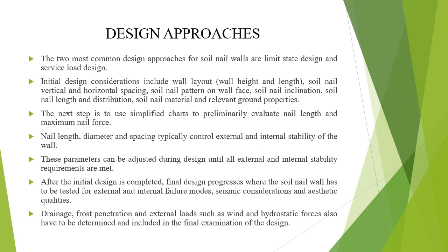These parameters can be adjusted during design until all external and internal stability requirements are met. After the initial design is completed, in the final design process the soil nail wall has to be tested for external and internal failure modes, seismic considerations and aesthetic qualities. Drainage, frost penetration and external loads such as wind and hydrostatic force also have to be determined and included in the final examination of the design.